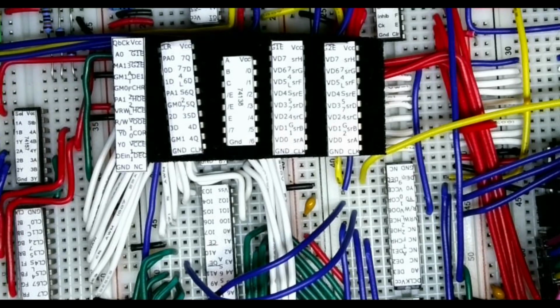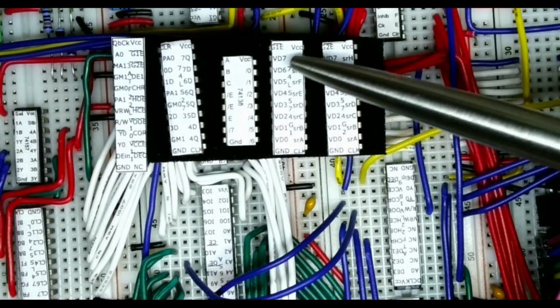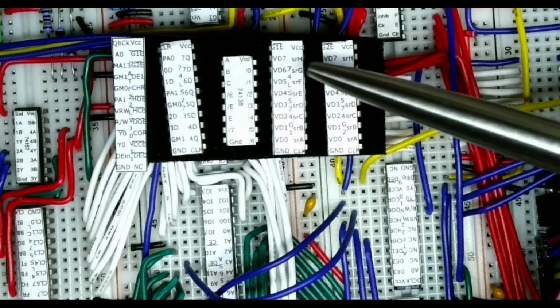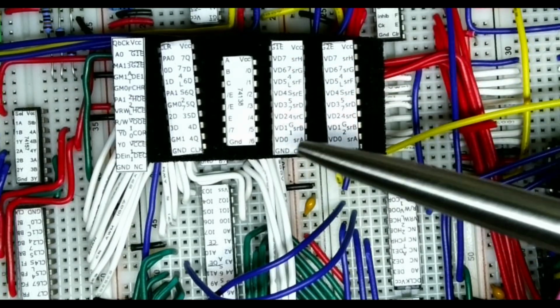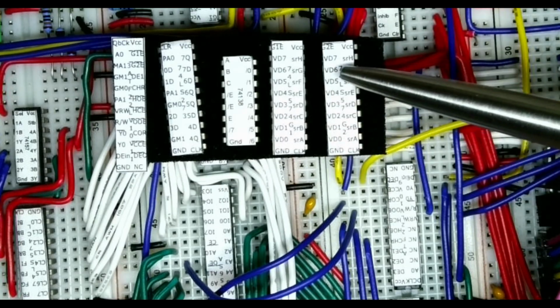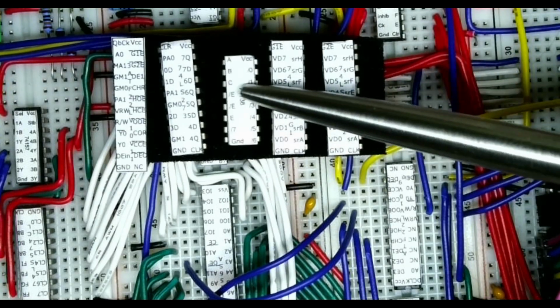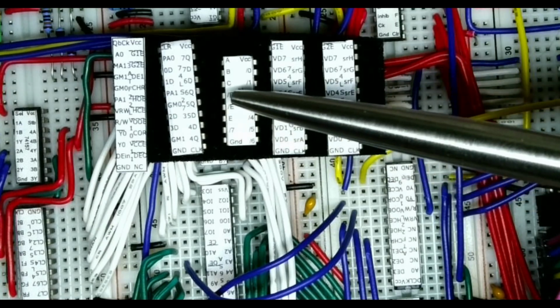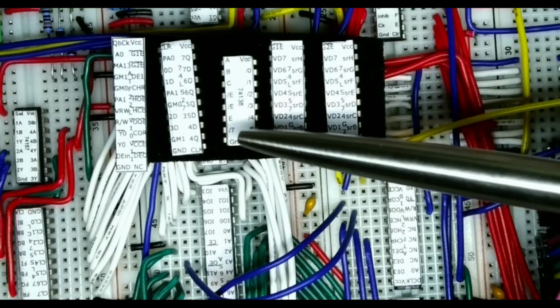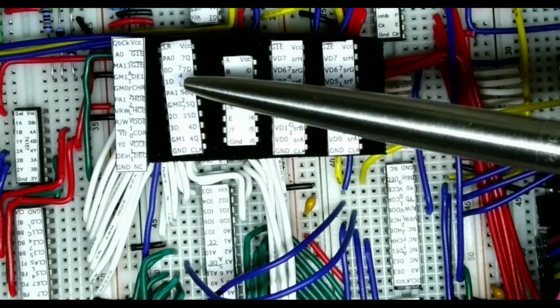So here are the chips. We've got two latches here for graphics 1 and graphics 2, and we can see the video data on one side, and then the shift register A to H on the other, just to make it a bit easier to hook up. We've got our address decoder here, which is going to break out our current CRTC line into multiple addresses so we can address various latches and things.